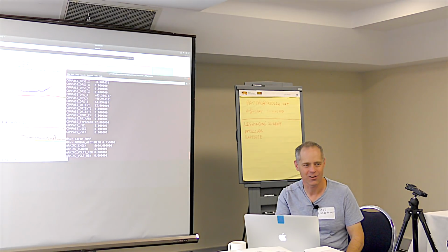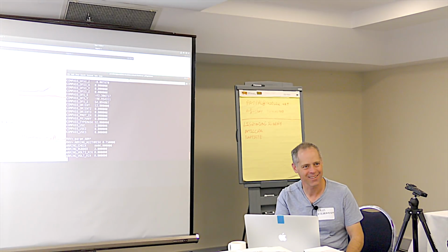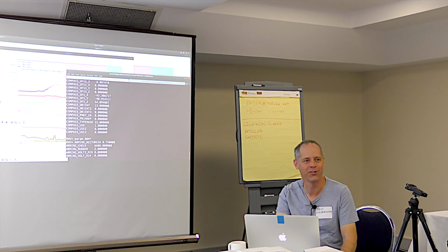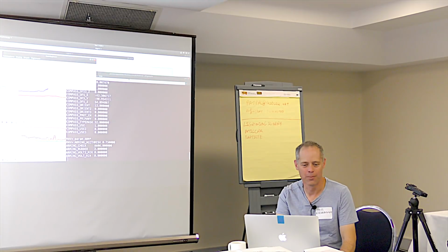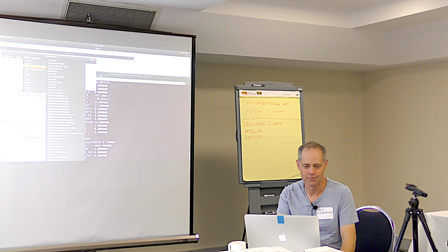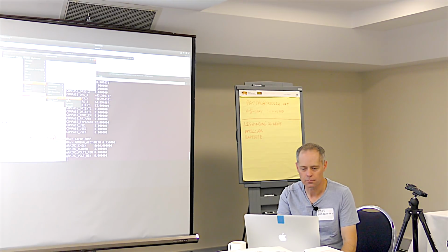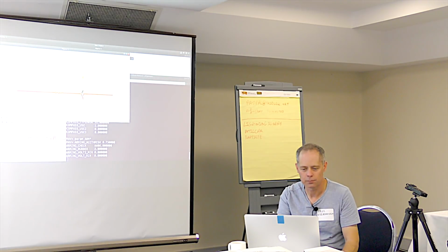Does he have the compass on? He's got compass on. Baro compass. Yep. Oh no, 60, that's decimal. Sorry, decimal. What's he turned off? So he's actually got 19 CE hex, which means he's got baro, compass, GPS, INS. He's got most things on. Yeah, so just turn the one that is off. He's turned off things like airspeed, logging is turned off. That's innocuous. Yeah, but most things are on.